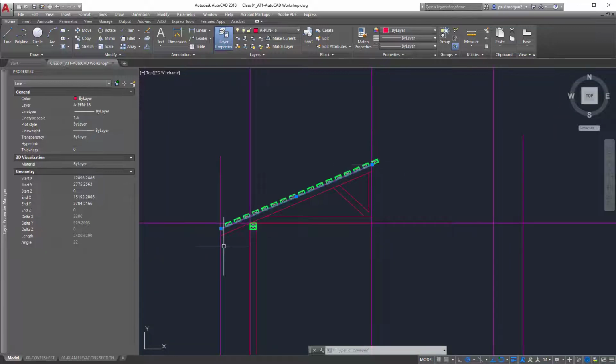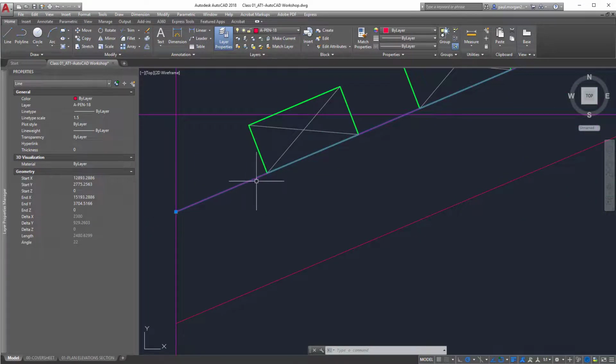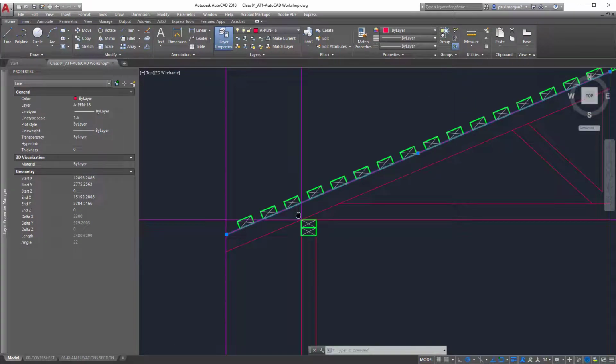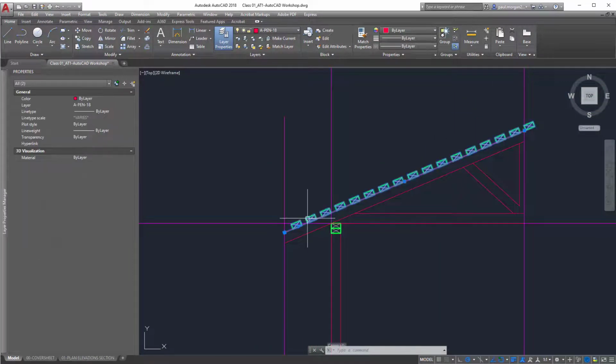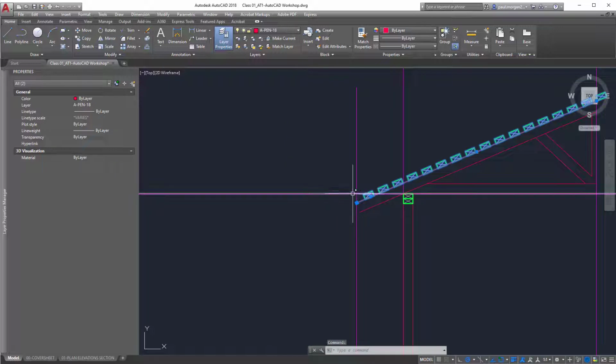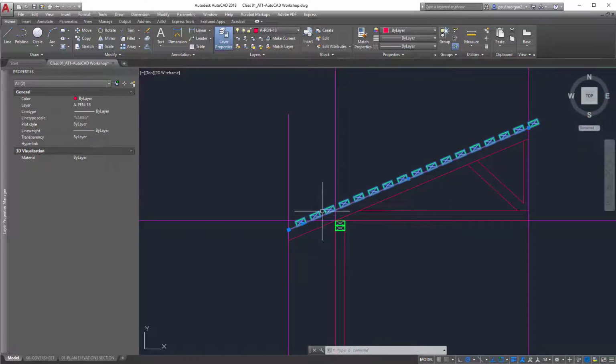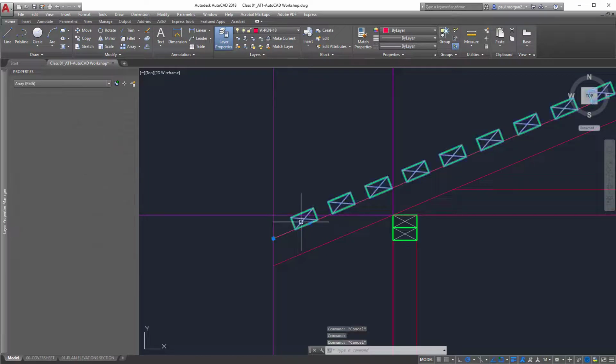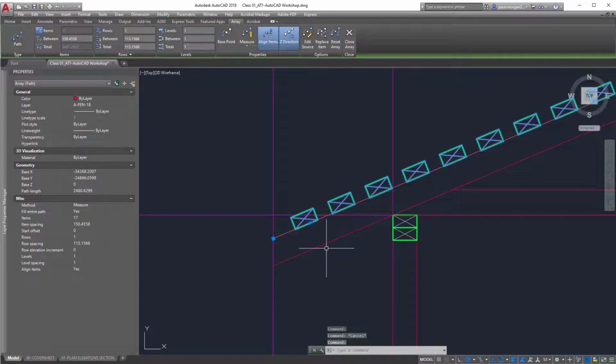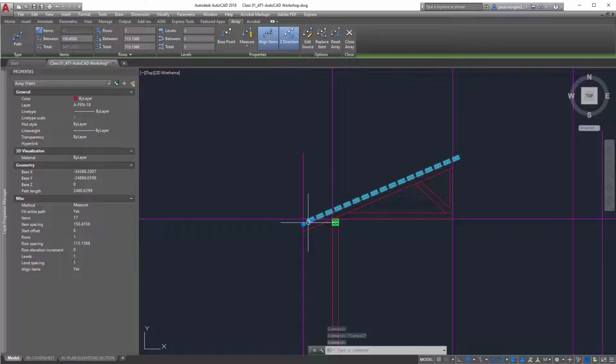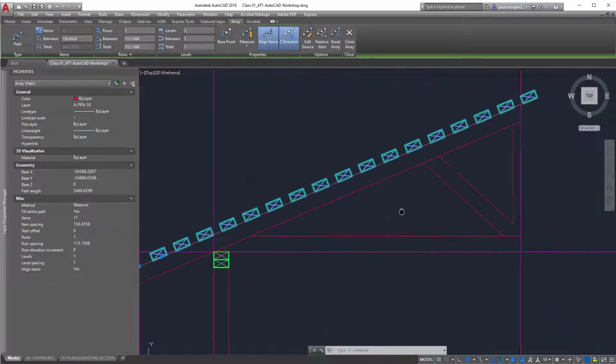That's why it's slightly overhanging, because I'm starting 90 mil into this line. Either way, that doesn't really matter. If your array is facing the other way and all these array elements are facing downwards, the best thing to do is just hit escape and then rotate the block that's sitting here 180 degrees, basically flip the object, and then it will array in the other direction.